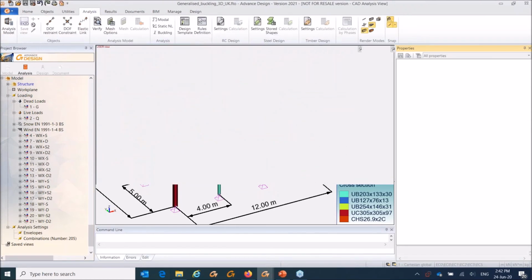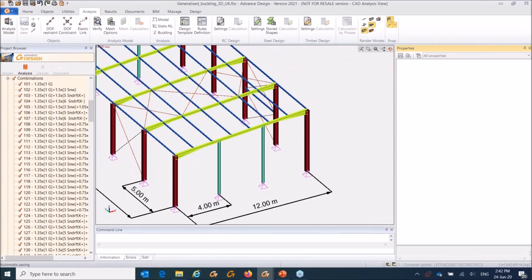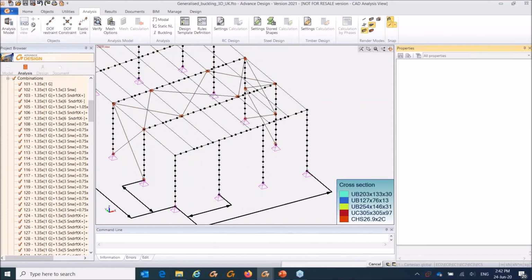Because I did perform a geometrical change, I have to run the analysis and design from scratch. So you will see the strong point of this super element is that you can calculate the deflection based on the total length and position of, for example, in here the gable post will be considered to create intermediate restraints for the rafter because you did split the rafter in 3. So we have quite a versatile option with this super element.